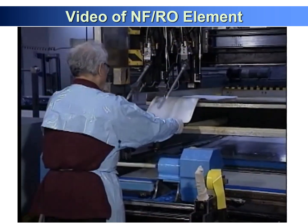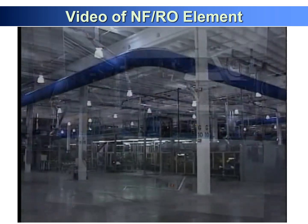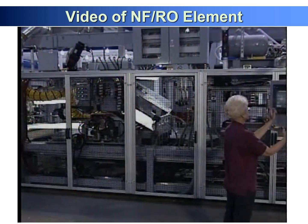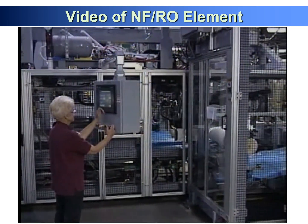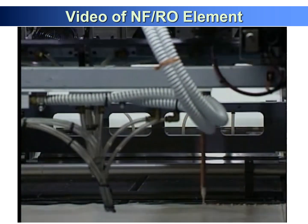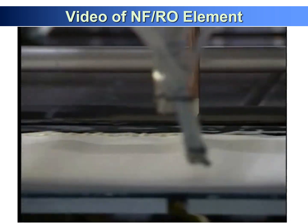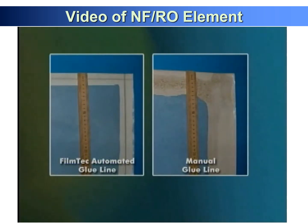A spiral wound membrane element can be fabricated manually or automatically. Dow uses custom-designed precision rolling equipment to automatically fabricate FilmTech elements because it allows for better, more consistent element performance. Sophisticated robotics for leaf construction and assembly ensure that every element is precisely built without membrane damage that often occurs during manual handling. Automation enables construction of more shorter leaves compared to manual rolling, resulting in a more efficient product that is less prone to fouling. Precise computer-controlled glue lines ensure the highest active area in the industry with guaranteed accuracy and minimize leaks, which can result in poor permeate quality.